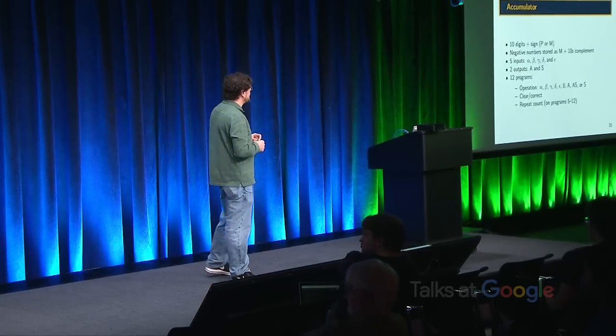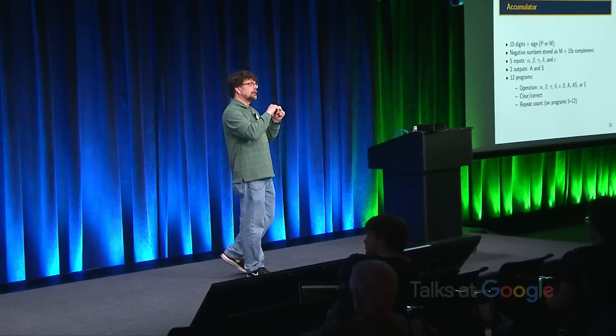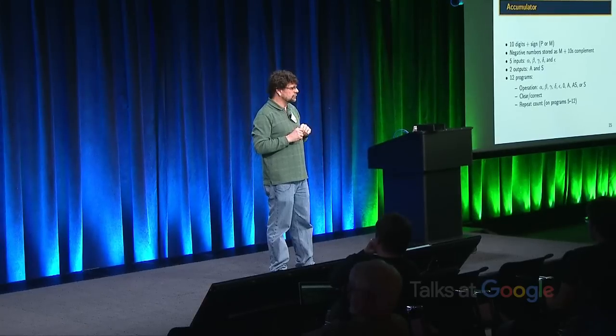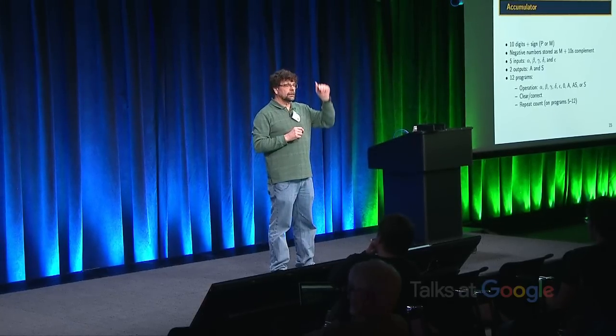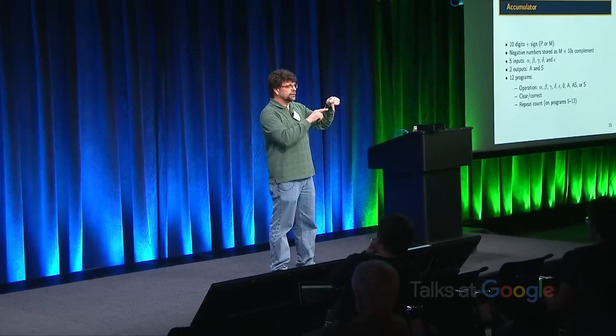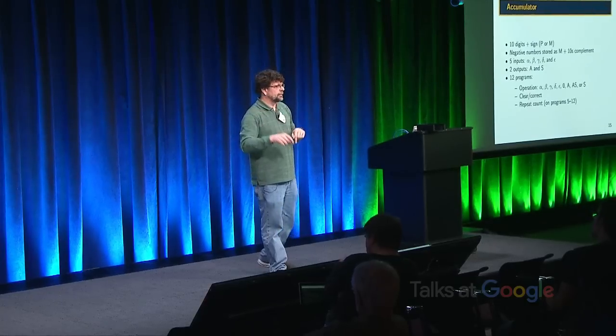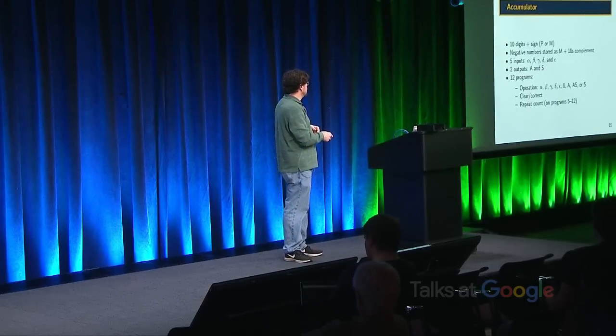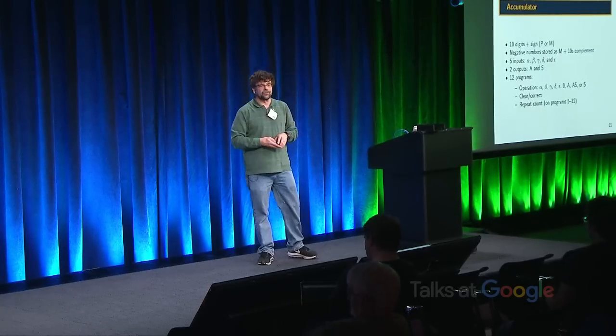The idea is that if I want to add, I'll transmit on the additive output, and whoever receives it will get that added to their current value. If I'm subtracting, I'll output on the S output, and then whoever receives it will get the difference. And the way it does it is by sending the number as it's stored on the A output and sending the complement of the number over to the S output.